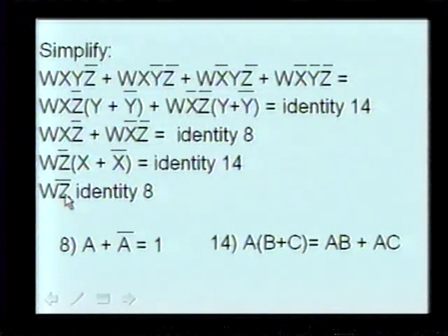So if you had a logic diagram and you had these gates right here, if you wrote it into Boolean expressions and simplified it, you'd come up with this. So if you were actually hardwiring your gates, this was very important to reduce the number of gates because it reduced the cost of your product. So it's very important to understand the Boolean identities.